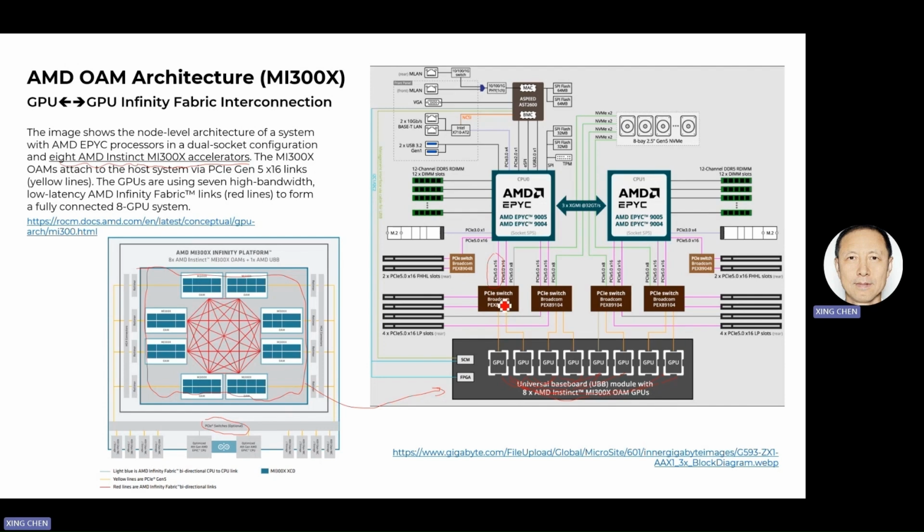Usually in the designs from the marketplace, the connection from the GPU to the CPU goes through a PCIe switch. At the same time, some slots are always reserved for the NIC, the interface for the network. Here we have two slots reserved for the first two GPUs, and another two slots reserved for the second two GPUs.